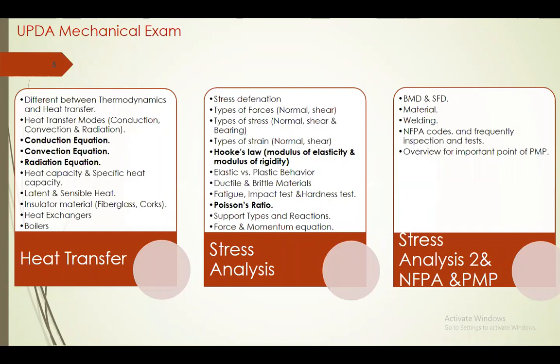Study the type of reactions and supports, and for each support, how many reactions, and what is the shape of this reaction. Is it force reaction or moment reaction, and which has one reaction, two reactions, and so on. This is important if the question is related to statics, and start by free body diagram to be able to solve the problem. Force and moment equation, bending moment diagram and shear force diagram, because some questions ask for this.